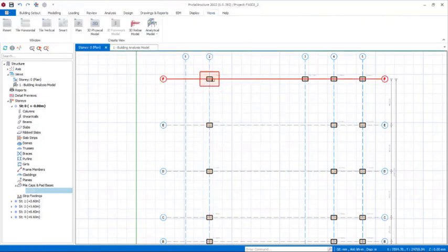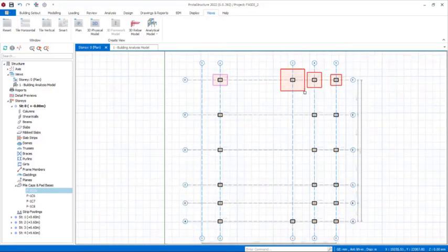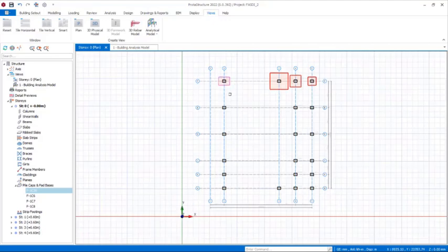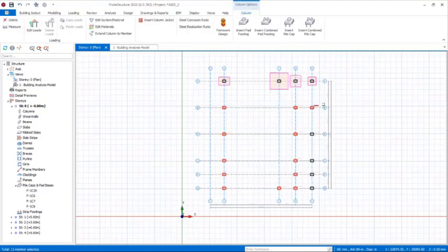With that same process, you have to insert your footing for all of these columns. So let us use the select all method. We click and drag a selection over all the columns, just like this. Hold the Control key to select the other one that has not been selected. After which you right click and then click on the insert pad footing option.